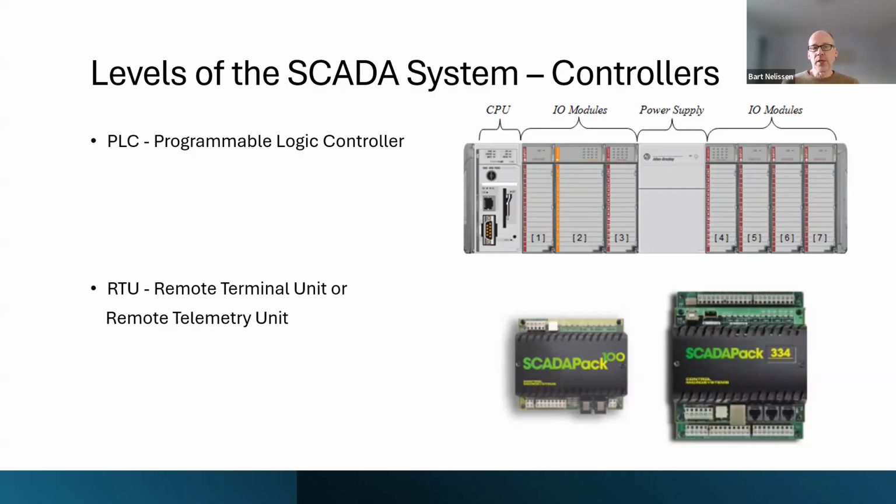The beauty of a PLC, before I move on, is that a PLC can be put together based on the needs and the instrumentation and all the devices out on the plant floor. So if you have a lot of discrete measurements, a lot of discrete control, then you can purchase and put together your PLC with mostly discrete modules, input and output modules.